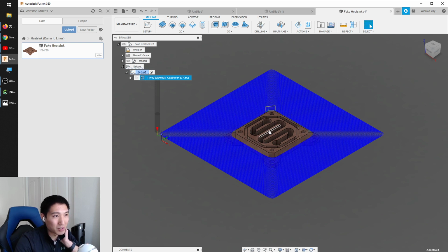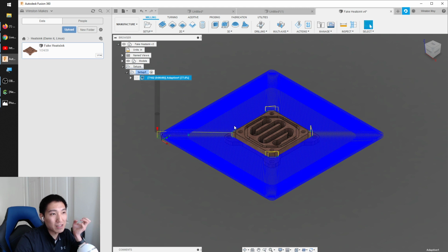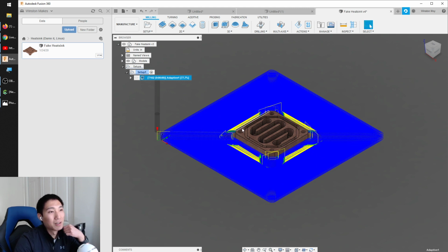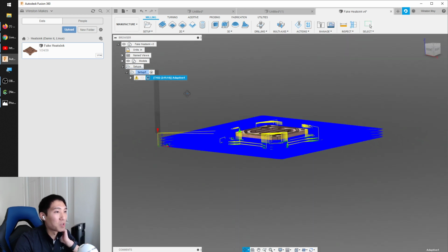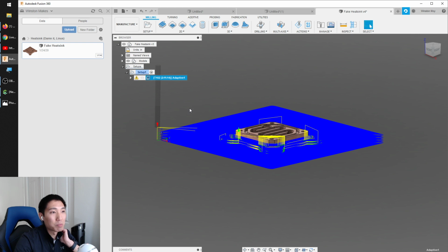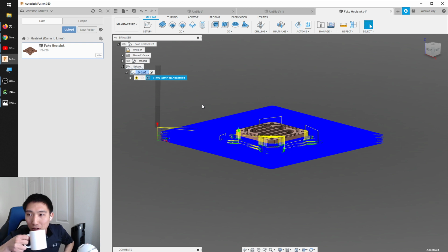So in these instances where you have a piece of material in a vise and only the top 80% is exposed and you're going to machine away everything, like you might do on an actual VMC, you would want to clear away everything. But if you have just a large piece of flat stock taped down to your wasteboard, you really only want the toolpath to focus on the part you're cutting out, and usually it's a 2D operation, so you wouldn't need to worry about this.